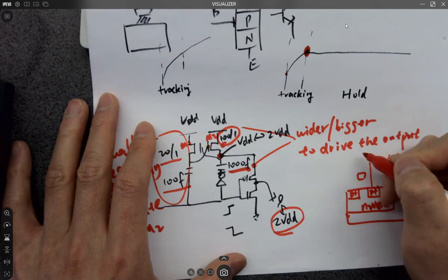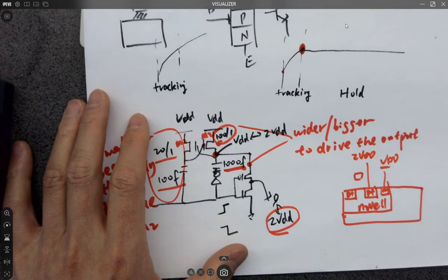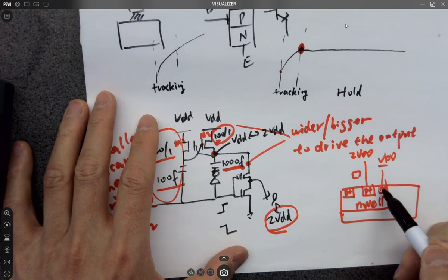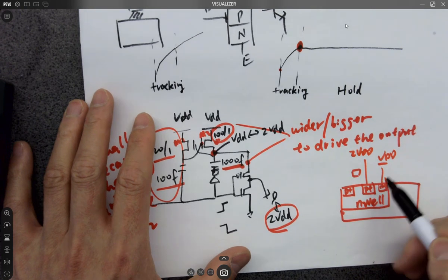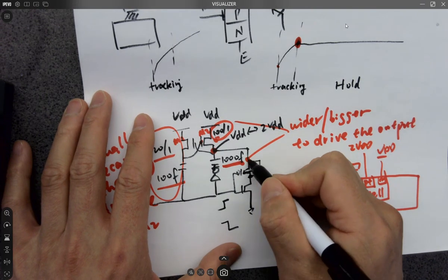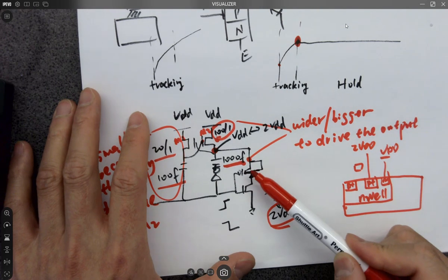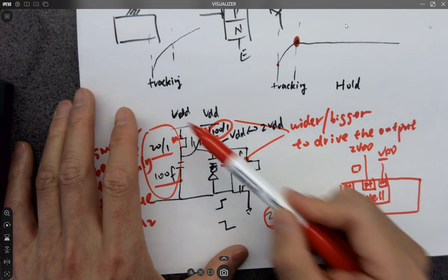However, this guy can potentially go up to 2 VDD, which is going to cause a PN junction to turn on, which is bad. So in that case, we want to connect the body of this PMOS to the source directly. So this PMOS has to be built in its own well, right? That's the third consideration for this circuit.